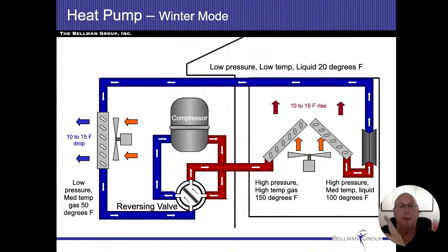All right. So now I'm going to have hot gas refrigerant going to the indoor coil, and since it's going to be cooler inside, I'm actually going to be discharging my heat on the inside. So as I'm discharging my heat, now what used to be my evaporator coil, it used to go from a liquid to a gas. Now it's going from a gas to a liquid.